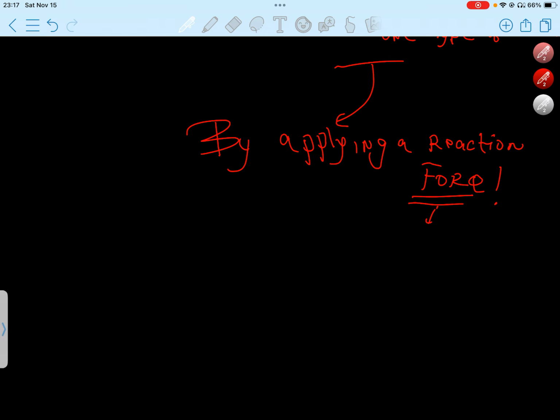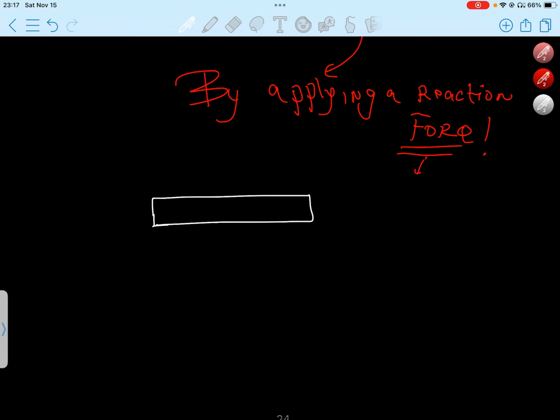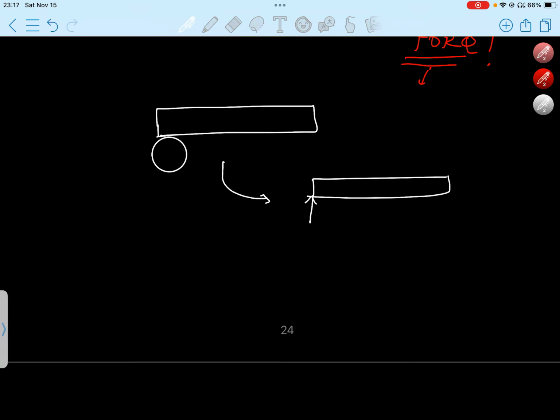Anyways, so if a roller is restricting motion in the vertical direction, then I think it's obvious that it would be applying a reaction force in the vertical direction to stop that motion, which is the reason why any kind of roller can be transformed into a vertical reaction force in a free body diagram.